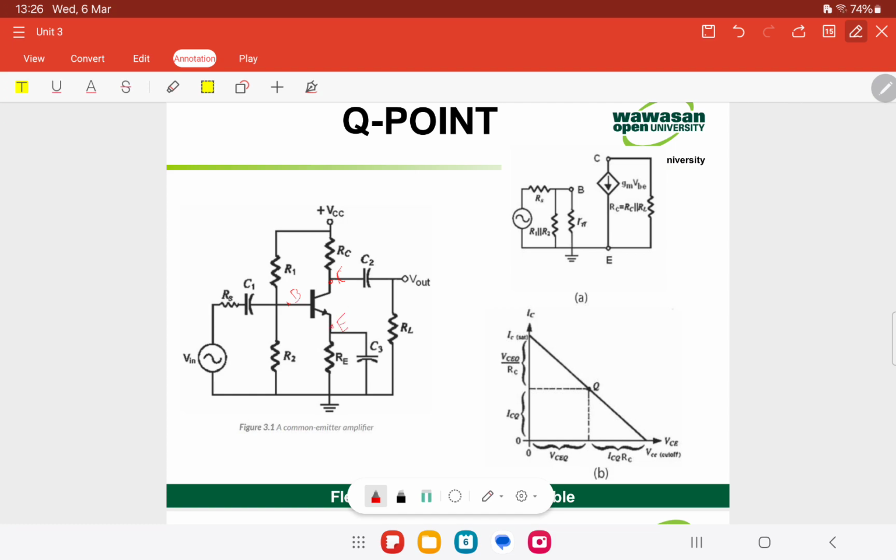Remember we have learned this in the previous subject on BJT. We have studied in bipolar junction transistor amplifier circuits that if the Q point is not centered, the maximum power would not be delivered by the amplifier. This is because it limits the maximum collector current at the collector and the collector to emitter voltage VCE swing.